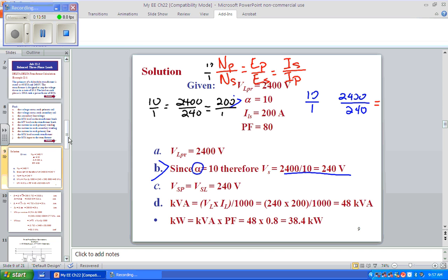Over current in the primary. And we can see that this is going to be 1/10 of this, so our current should be 20 amps, right? Would anybody go with that? Yep. Is that correct? So why does it say, oh, it's getting the kVA on the primary. This kVA right here is coming from the primary, I believe.